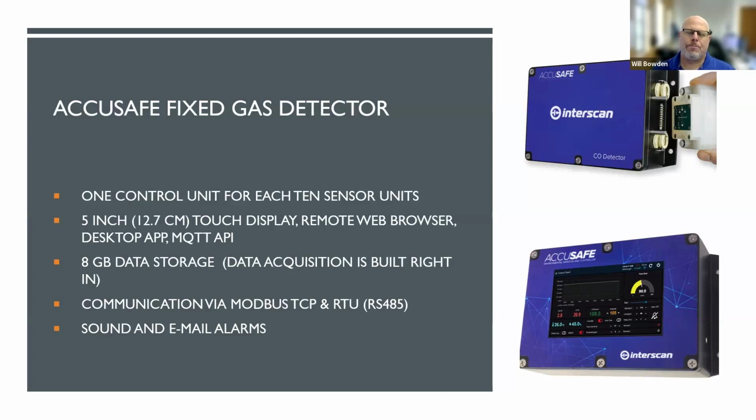The screen's roughly 5 inches and also includes the ability for remote web browser. Since we have that RS-485 communication protocol built in, you could take this and actually interrogate the instrument itself back at your laptop, desktop, wherever the case may be. Data acquisition is also built into the AccuSafe with 8 gig of data storage built in on board the control module itself. As I mentioned previously, communications via Modbus, TCP, and RTU, the RS-485.